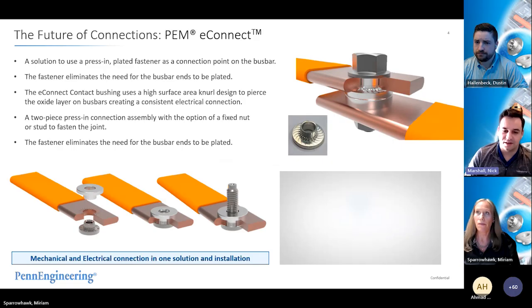What we're showing here is a product that we've been developing specifically based around this need. This is our eConnect contact bushing, which is designed to create that high current conductive, low resistance joint from bus bar to bus bar. What we're doing with this part is we are using a small copper element that we forge, and then we plate with silver or tin or nickel, depending on the needs of the application, and then we install into the end of the bus bar.